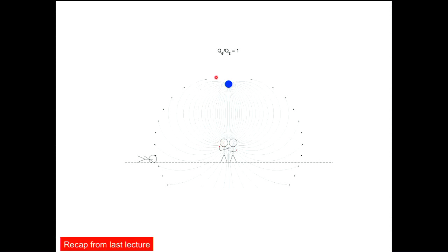to track these particles. So what I showed you for my code was a very simple Euler time-stepping scheme, which is first order accurate, but you are expected to use RK4 in your assignment, which is fourth order accurate. Okay, and again, that will be elaborated more in your MATLAB workshops.